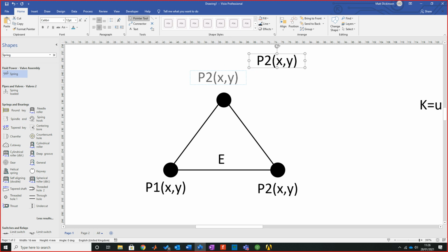Anyway, we've now added one in, and this is as simple as it's going to sound. If I copy that in and paste that above, now I say, right, we have P3. We know that Young's modulus is attached equally all throughout. You don't decide this. It just says this is Young's modulus on all elements that's there. But this is for volumetric, isometric materials. So basically, the Young's modulus is equal in all three component directions.